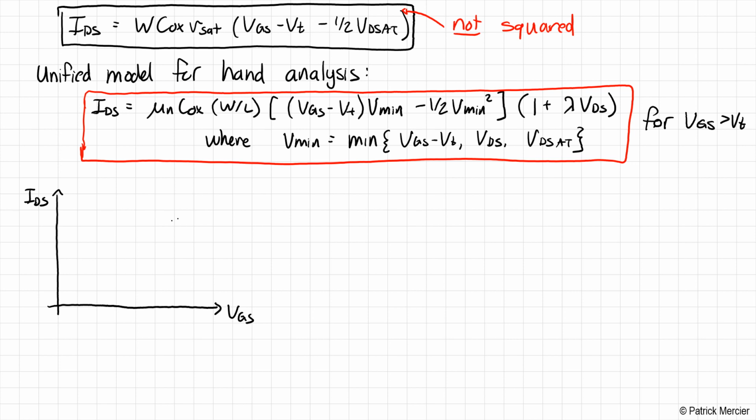Okay, so normally this is supposed to be 0 until we cross the threshold voltage, and then we are quadratic. Okay, this is what we'd call the normal saturation regime. And then this here is approximately the threshold voltage. So below that we're in the cutoff regime, and then after that we are saturated. Now in actuality, if we are velocity saturated, then this basically becomes a straight line. Okay, so this is velocity saturation.